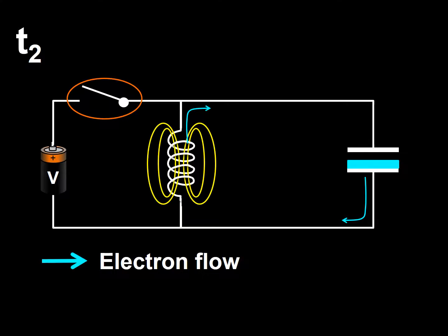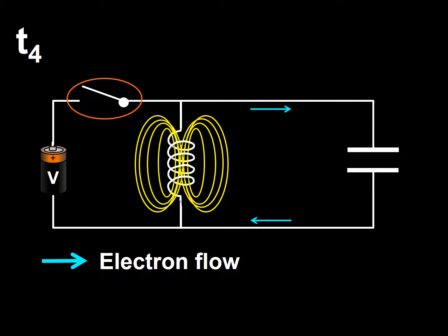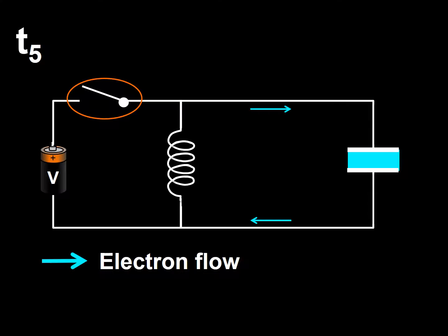Thus, despite that no voltage is being supplied by the battery, voltage will be available on the side of the capacitor and the inductor. In this fashion, the inductor will feed the capacitor and the capacitor will feed the inductor. Thus, the inductor will be discharging when the capacitor is empty, and the capacitor will be discharging when the inductor is empty.